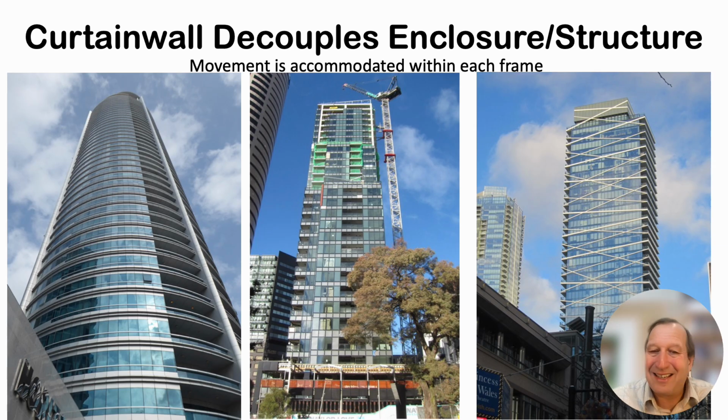The glass slides inside of a slip joint, and that allows movement. There are times, particularly in high-rise buildings or buildings with lots of lateral movement, like earthquake zones, where you actually have to make the frame that holds the glass quite a bit wider to accommodate the fact that you need a lot more. I mean, if you need 2 inches or 50 millimeters of movement, well, then you're going to need a bigger frame.